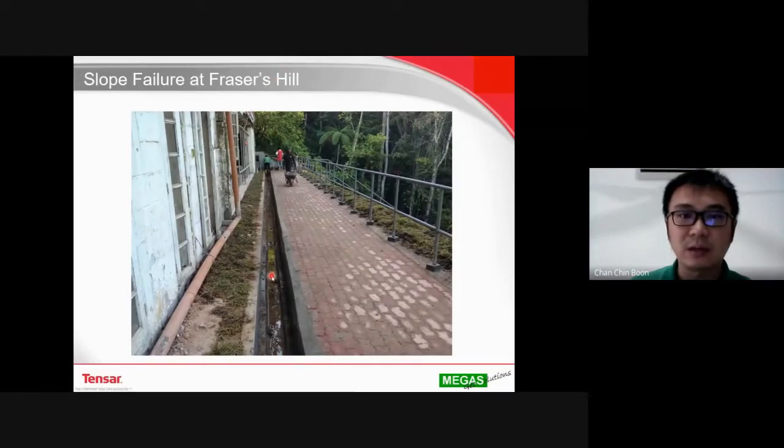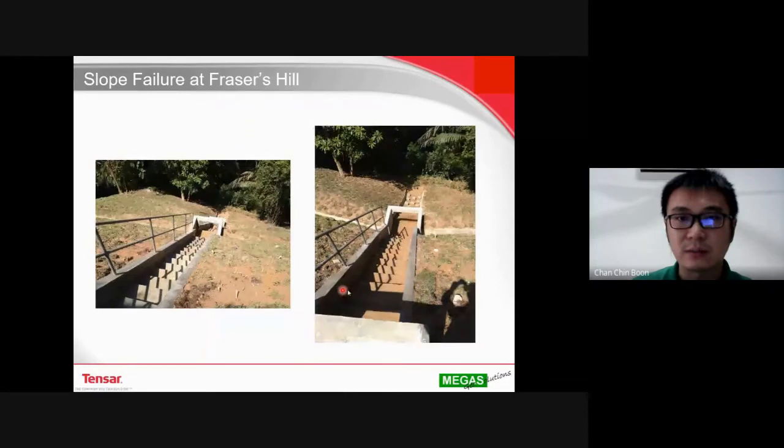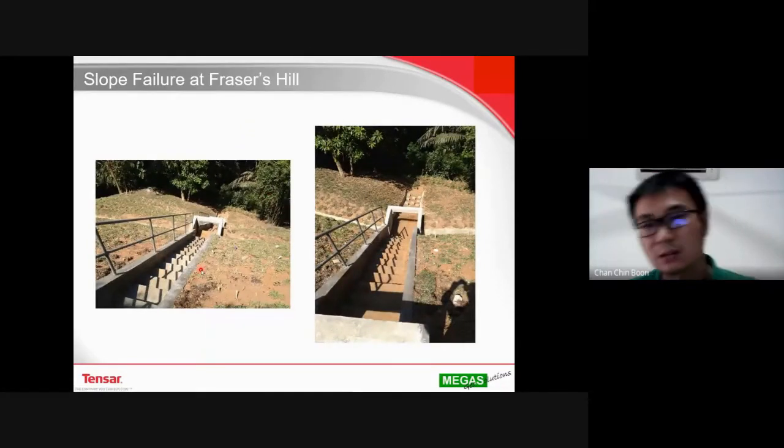And the drain, this is an interceptor drain that we provide right after the gutters below the building, so it can collect the water as much as possible without rushing to the slope. And whatever water comes out, water pipe or whatever, it comes out from the building is able to be cut off by this interceptor drain and then drain away. Okay, drain away somewhere here. The dome drains, cascade drain, as well as a staircase for them to carry out the maintenance in the future.